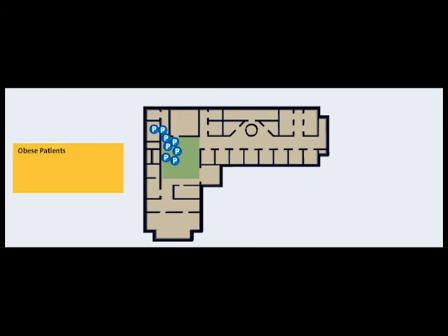For these reasons, consideration should be given on a case-by-case basis to evacuating these patients last, when maximal resources can be brought to bear and the risk of blocking evacuation routes has least impact. Note that the priority in an urgent evacuation is efficiency, requiring clearance of corridors and stairwells as quickly as possible.